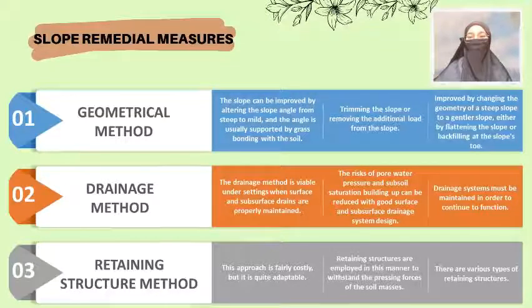Trimming the slope or removing additional load from the slope can be used to carry out this strategy. It also can be improved by changing the geometry of a steep slope to a gentler slope, either by flattening the slope or backfilling at the slope toe.